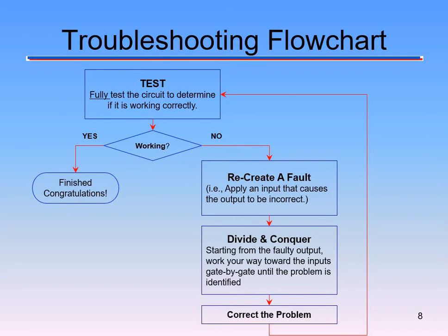Or eventually all those don't work out. Is the chip bad? And you do a basic circuit to check the chip. Very, very simple things. But it might take you a few times through. Sometimes wiring something correctly creates a fault in another part of your breadboard that you miswired. So you just gotta be careful, but do one step at a time. Don't take everything off your board and start from scratch.